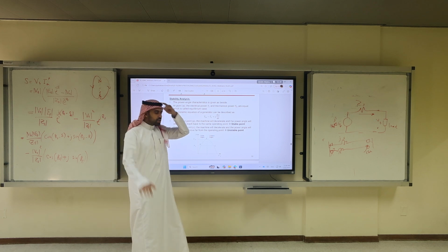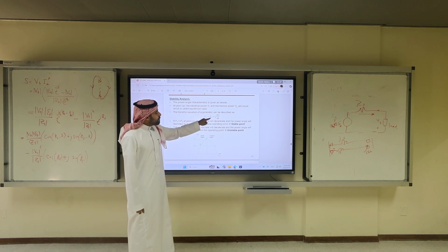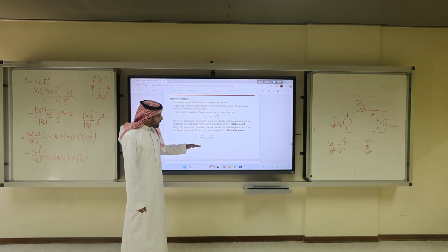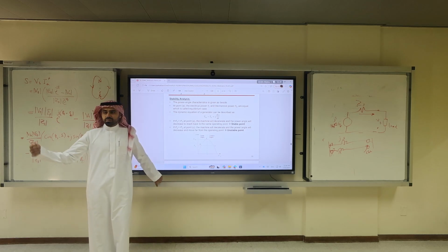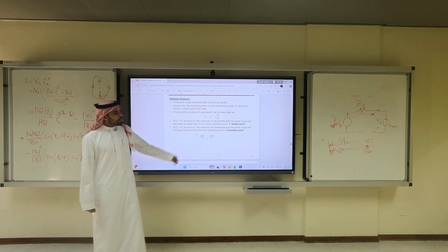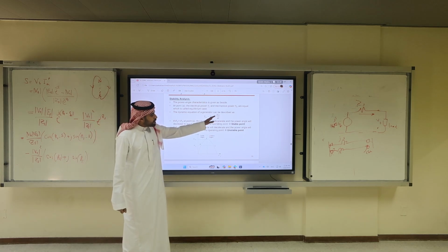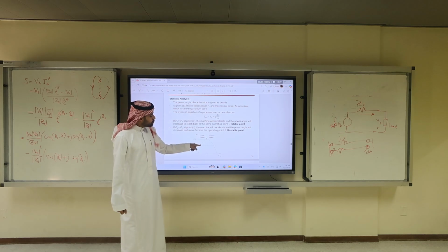If I'm having more torque in the electric machine, I'm coupling it with the mechanical engine, which is fixed by command. I know how much diesel I burn, it's fixed. The electric generator would have a negative acceleration, so it would decelerate back to the equilibrium point.